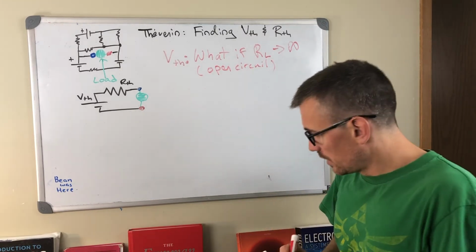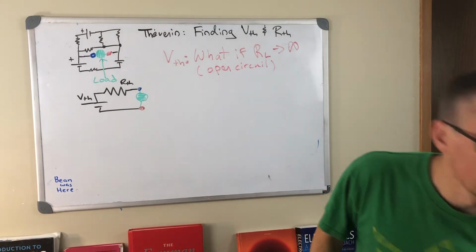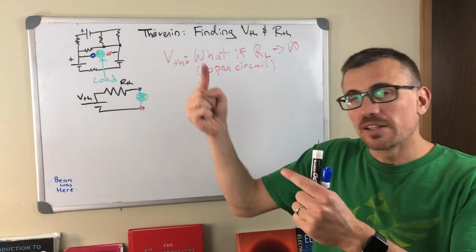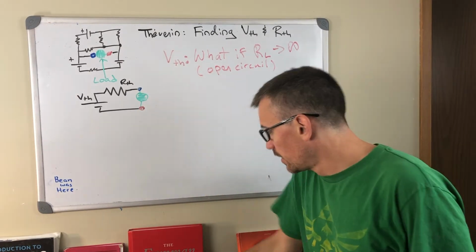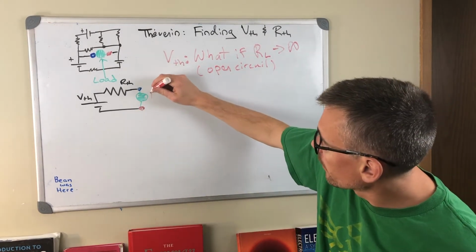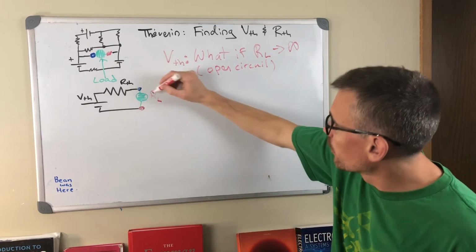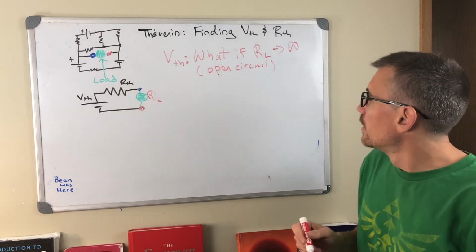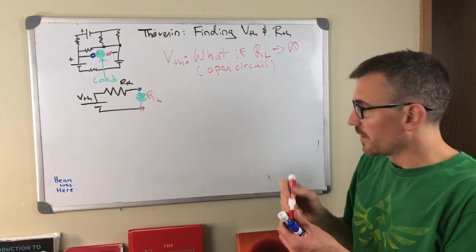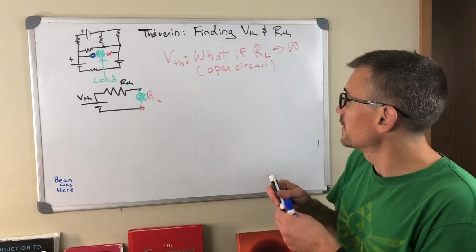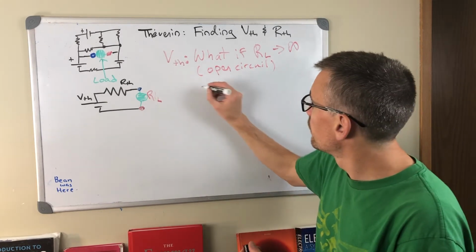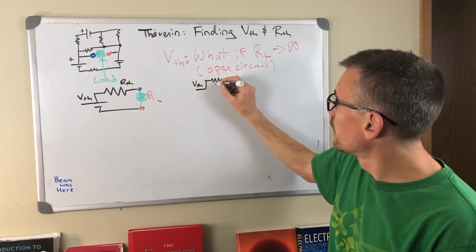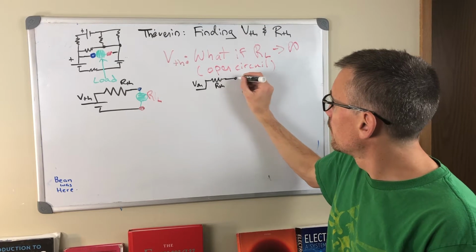All right, here's the easiest way to make an infinite resistance on this wire: snip. You just chop the circuit, you open it, and no current can flow. We'll call this green one here RL. So RL goes to infinity. Well, our circuit is quite simple in this case. In this case, we have V-Thevenin in series with R-Thevenin.